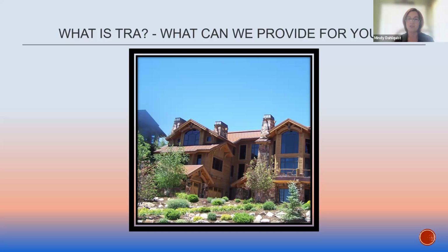And then if you're trying to get a complete airflow into the attic for a cold roof system, you would want that insulation lower, because you're actually wanting to equalize the back side of the roofing material to the outside temperature. So you wouldn't want that insulation to be sitting right there.